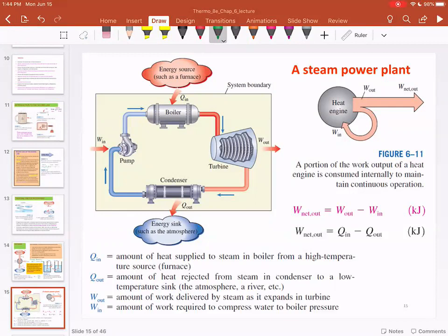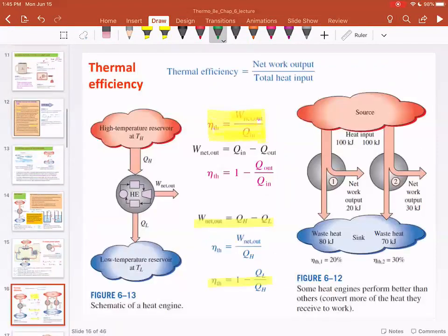And then low pressure, low temperature steam is exhausted in the condenser, and in the condenser the steam cools down and gets converted back to water, and that water can now be pumped again to the boiler, and this process can continue. So that is how a steam power plant works.